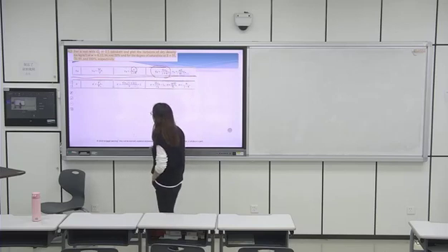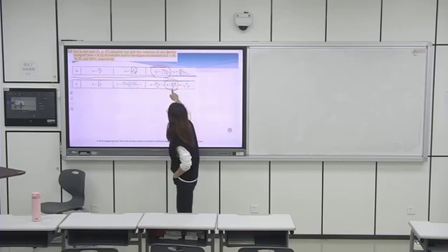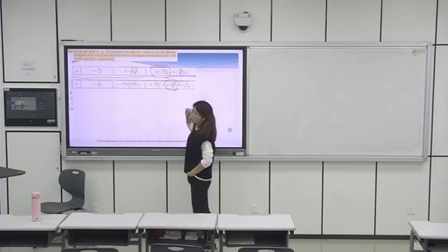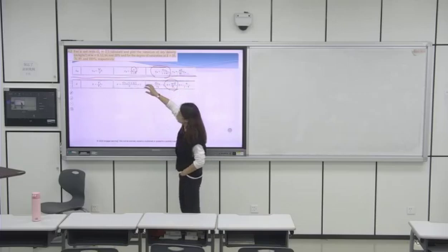Can we do that? Let's see what the void ratio is. Void ratio equals this. We can use this to calculate the void ratio, right? Water content we know, Gs we know, S we know. We can calculate every single void ratio corresponding to different water content and saturation degree.